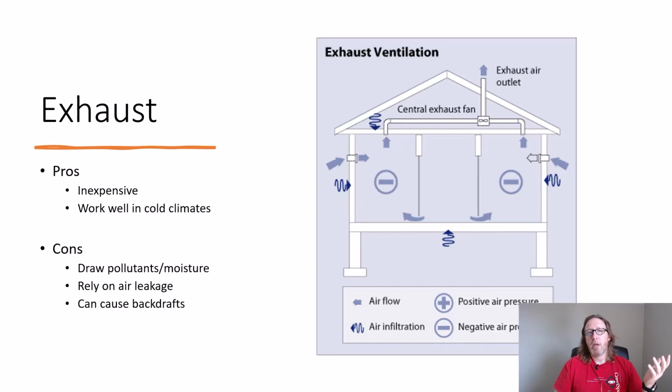For example, turn on the bathroom fan. This is what happens, okay? So this is an exhaust fan. I'm trying to move the odor out of the bathroom, out of the house. Well, as I do that, if you put your hand under the door of the bathroom, you'll feel the makeup air coming under that door to make up the air that's being pushed out of the bathroom from above. So that's a good, simple example of how airflow works, all right?